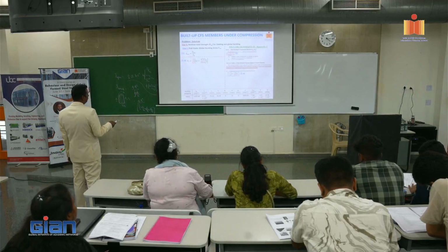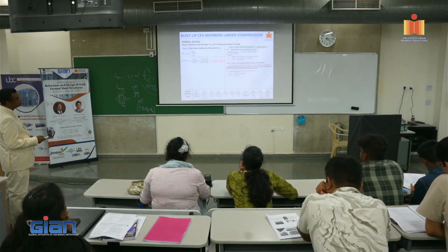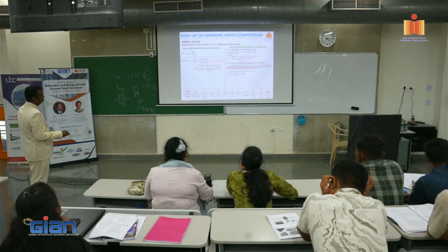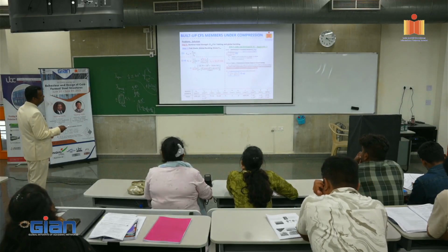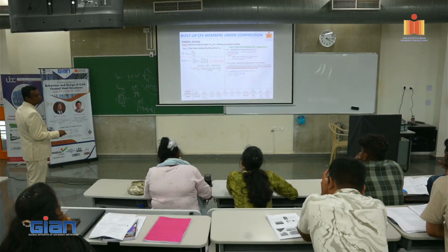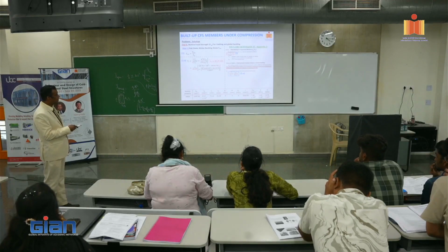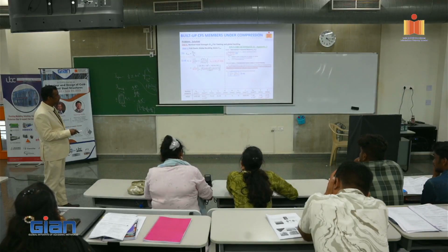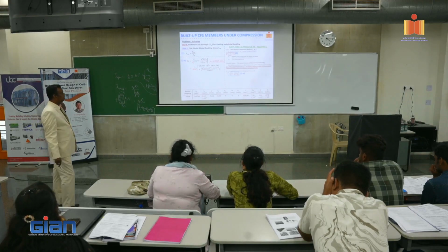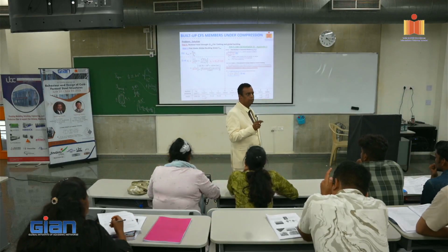Now this R naught square we have already calculated it, right? So we know that R naught is equal to 82.25. We put this value, G is 0.78 into 10 power 5, plus pi square. J is 181834, right? The J is 2 times of something, so 2 times 917 something, you get 1834, plus pi square E, which is given as 2.03 into 10 power 5, CW is given as 7.48 into 10 power 9 divided by 1800. 1800 is because there is actually a restraint there. Instead of 3600 you take 1800, right?